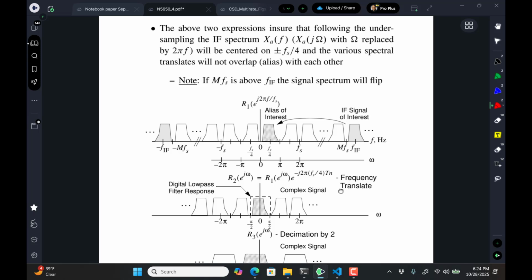And if vestigial sounds weird to you, it's a word in the dictionary, right? A vestige would be something that's the remainder. It's like the big thing is here, but the vestige of it is the smaller thing. And in modulation theory, most modulation schemes end up with a two-sided spectrum centered on a carrier, and if you can eliminate one of those sidebands because you don't really need it, that saves a lot of bandwidth. It allows more signals to be packed together. But there are a lot of other techniques in digital comm that manage that too.